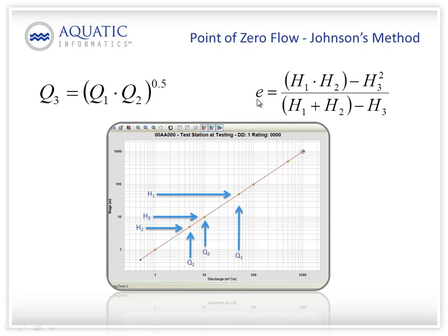So really the preferred method is to come back from the field with a pretty good idea of what the offset should be, what really makes sense, and have an idea within a fairly narrow range of values. And then within that range of values, manipulate your scale offset until you see your measurements plot in a nice straight line.